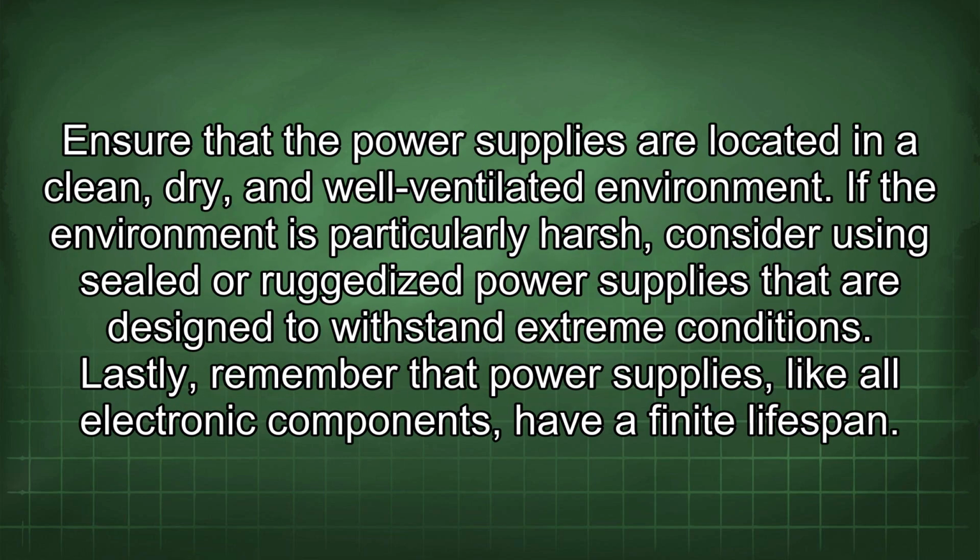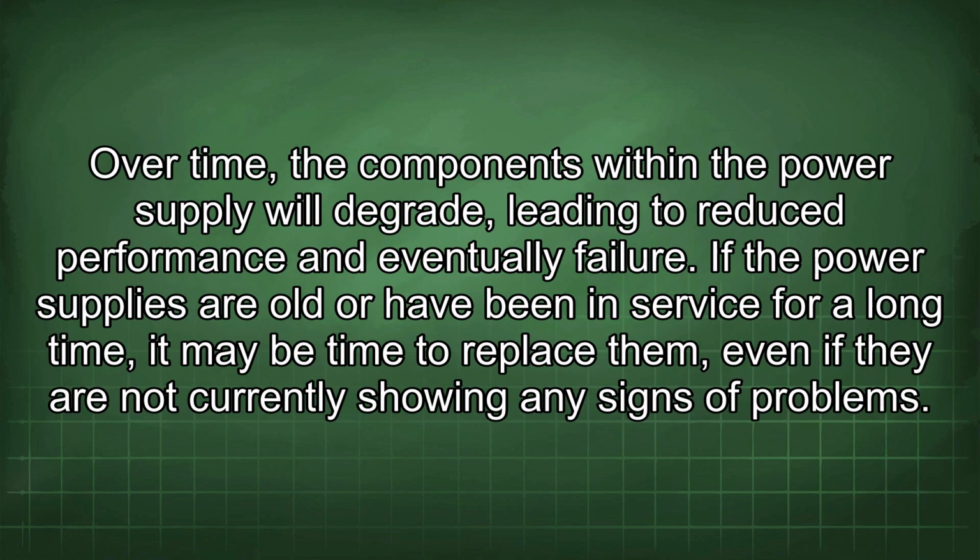Ensure that the power supplies are located in a clean, dry, and well-ventilated environment. If the environment is particularly harsh, consider using sealed or ruggedized power supplies that are designed to withstand extreme conditions. Lastly, remember that power supplies, like all electronic components, have a finite lifespan. Over time, the components within the power supply will degrade, leading to reduced performance and eventually failure.